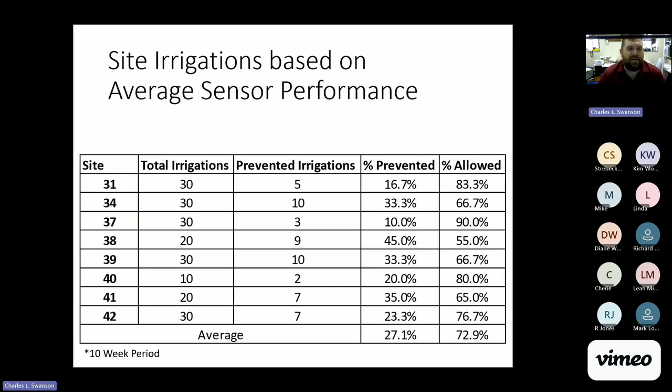Did you irrigate on Monday, but it rained on Tuesday, and then vice versa? And so we had this nice subset of unique schedules that homeowners were implementing on their own to evaluate the potential. And we can see here, there is potential to where you could save upwards of 45% if your schedule just aligned perfectly with the normal rainfall pattern during that season. In other cases, the sensor didn't produce very much savings at all. But I think we're comfortable saying, on average, 25% savings just by having a rain sensor on the controller.